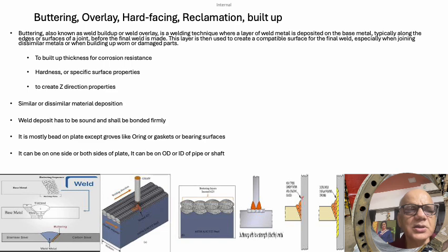And the third application is like a lamellar tear, as you see here in this particular sketch. This layer which is given here is to prevent the lamellar tear, which happens because when you have very thick rolled plates, in the Z direction the sufficient grain orientation doesn't get, the compaction of the grains doesn't happen in the Z direction, and that's where we get a lower strength.